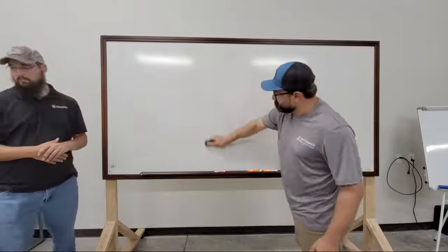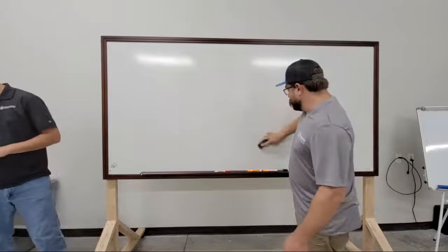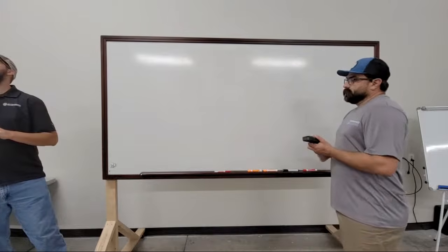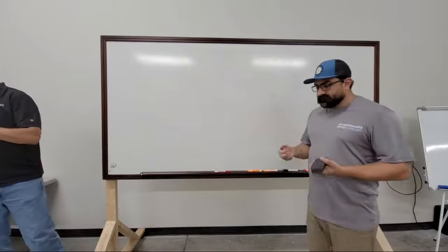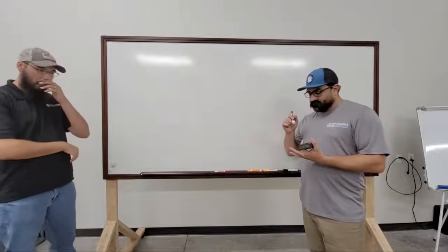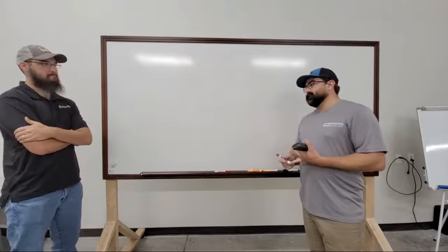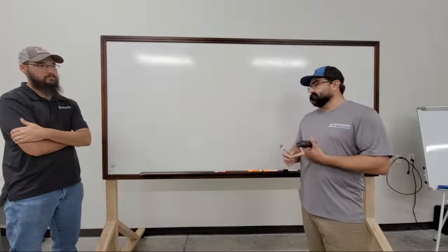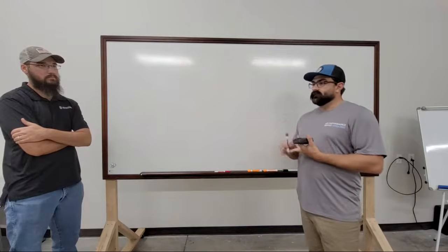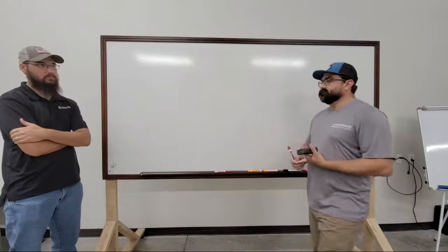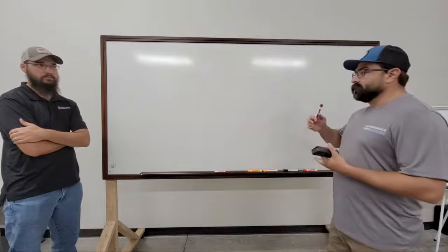We have a few specific buildings that have it, and it is always problematic. Basically, you're increasing your failure points with any dual duct system. You've got two cross flows, you've got two controllers a lot of times, you've got a minimum of two actuators if you don't have two controllers. If there are multiple controllers, they have to communicate with each other, talking back and forth.